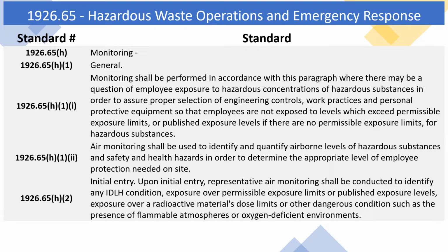protective equipment so that employees are not exposed to levels which exceed permissible exposure limits, or published exposure levels if there are no permissible exposure limits for hazardous substances. H1 2. Air monitoring shall be used to identify and quantify airborne levels of hazardous substances and safety and health hazards in order to determine the appropriate level of employee protection needed on site.